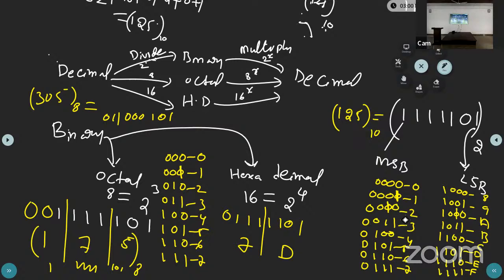To design the read-only memory or random access memory, the RAM or ROM, we are using flip-flops. The flip-flops are made up of the logic gates. There is an AND gate, OR gate, NOR gate, XOR gate, exclusive OR gate. Mainly the AND gate or inverter. After that, NAND and NOR gates. Using these gates, we are making the flip-flops. A flip-flop is a 1-bit storage device. For example, if you want 8-bit data, you can add 8 flip-flops. You will get the 8-bit register or 8-bit memory data.